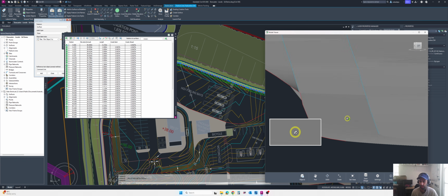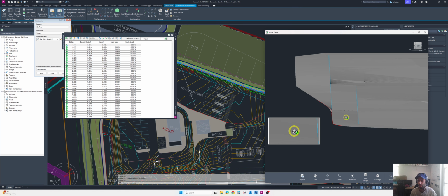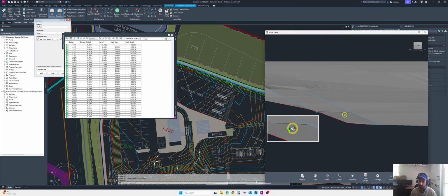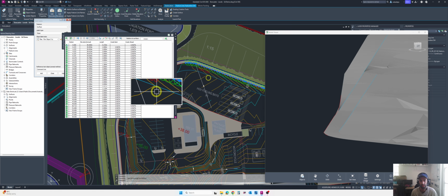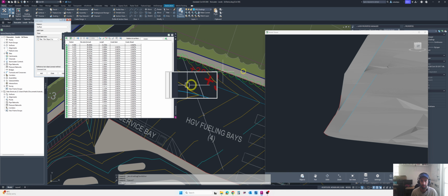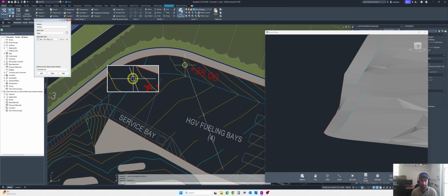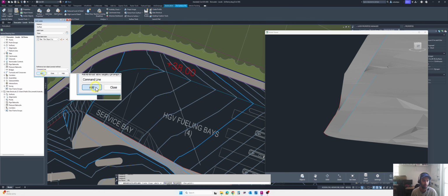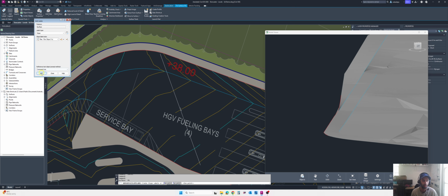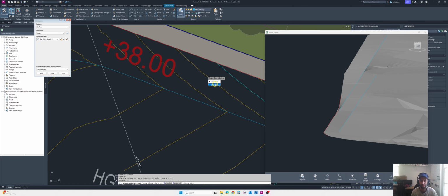Now in the 3D you can see the road is properly looking, so I think it should be fine. Yeah, no rough points. Also we will see the crossfall of the roads. So I will select this one and select the surface again, and then add a point, add the surface, 2 points, select this one to this one.